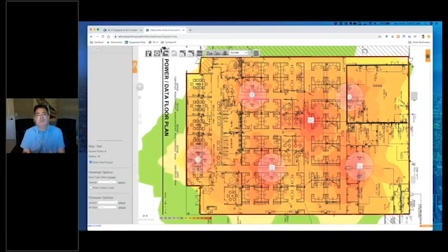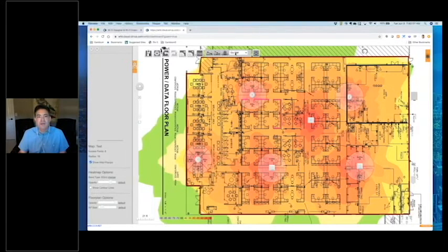You can measure the attenuation on one side and then the other, and look at the propagation difference, because every metal door is different. We have these options here in the drop down, as I talked about earlier. And maybe the brick wall can be used to emulate that metal door depending on the attenuation level. So I think it's a good point to understand these attenuations a little bit more specifically, and that's something that we can document. Okay.